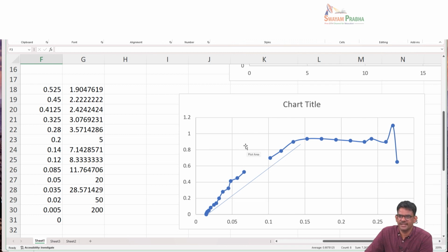It is solid controlled drying, exactly. In the unbound moisture drying, which is the constant drying rate period, the drying is controlled by the gas phase. So if you change the gas phase property, it is going to change, whereas the falling rate is broadly controlled by water diffusion inside the solid. Whatever you do on the gas side may not affect it so much. It is driven completely by the internal mass transfer within the solid. So we can fairly assume that it is not going to change much when we change the drying conditions outside. So that is the assumption that you are going to make, and using that assumption, you can make this calculation.